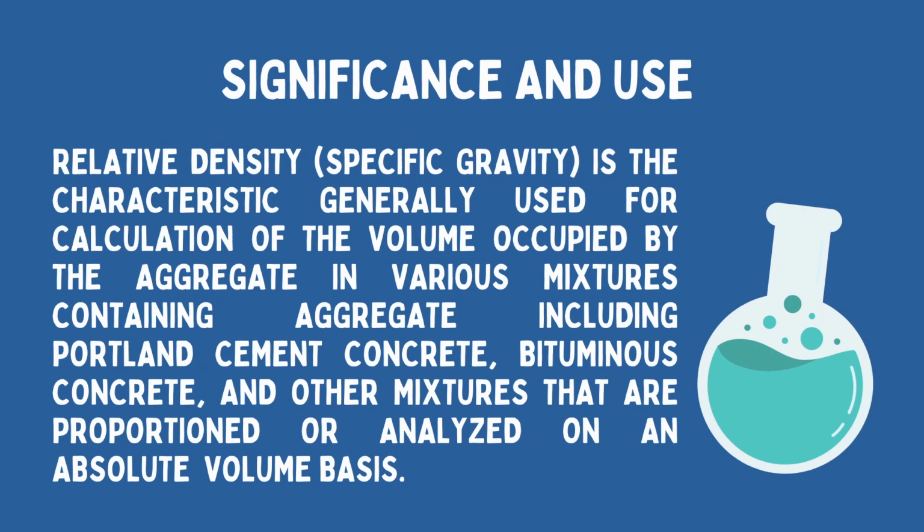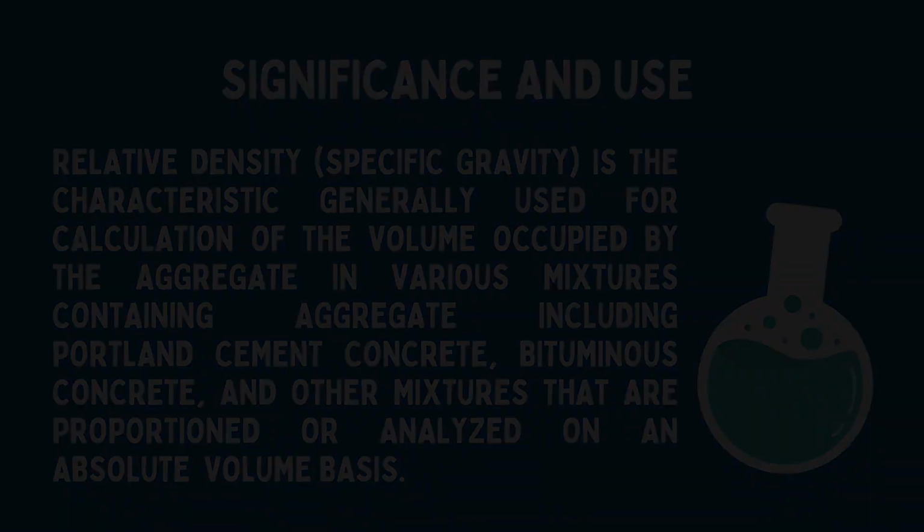Significance and use: relative density or specific gravity is the characteristic generally used for calculations of the volume occupied by the aggregate in various mixtures containing aggregate, including Portland cement concrete, bituminous concrete, and other mixtures that are proportioned or analyzed on an absolute volume basis.